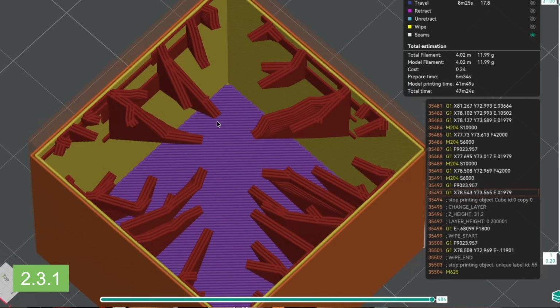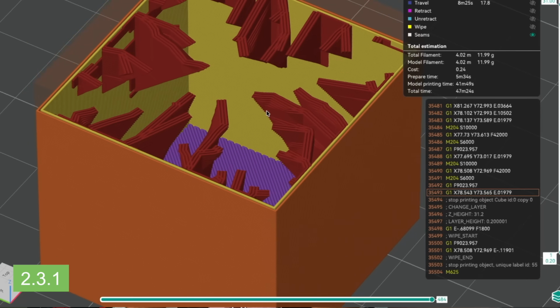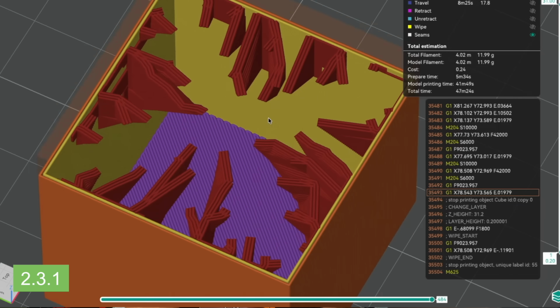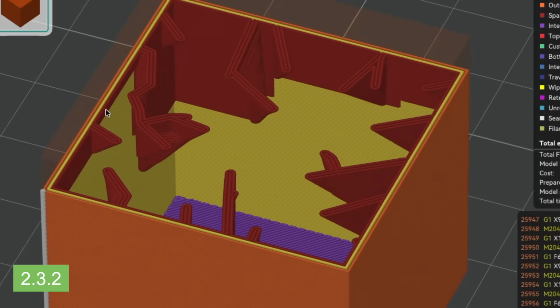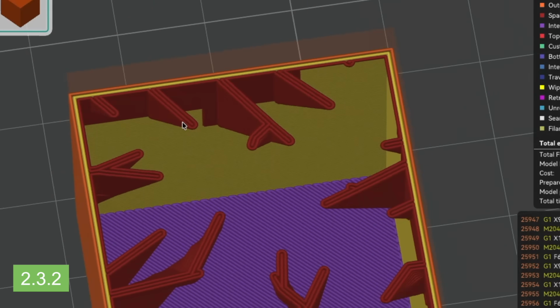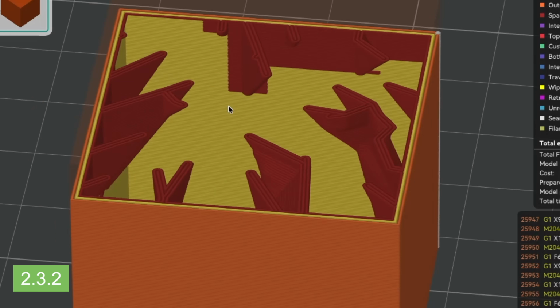Multiline infill is now properly anchored to the perimeter, while before in some cases it was just sort of loosely connected or floating altogether. While I still don't recommend using something like lightning infill for demanding applications, this update does improve the part's overall strength.